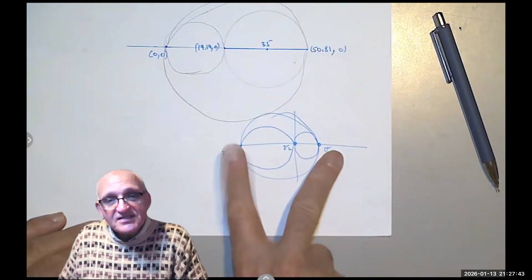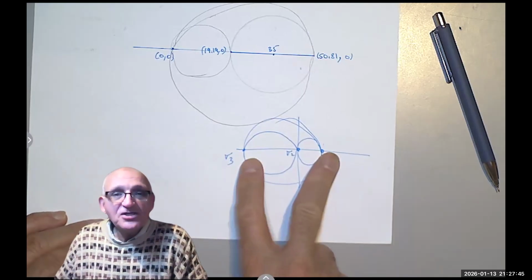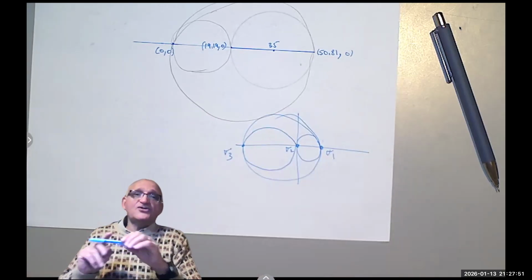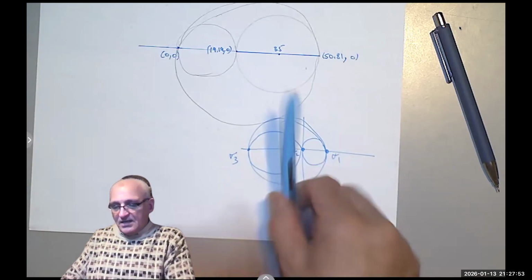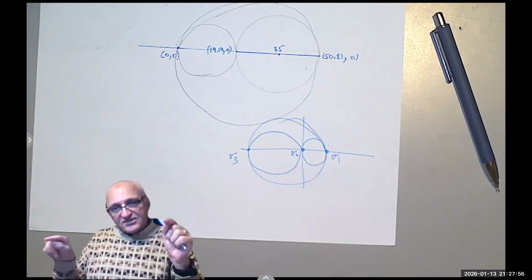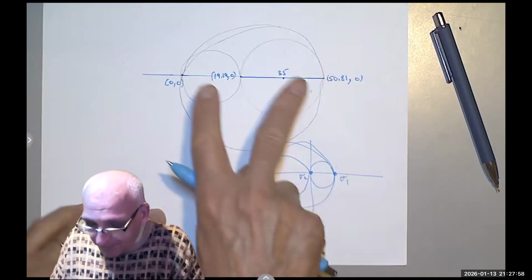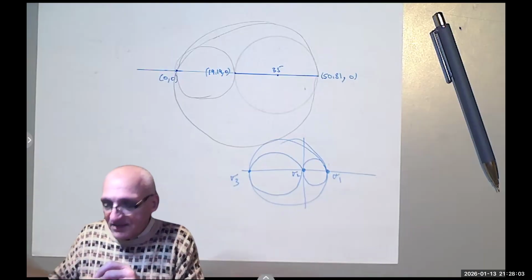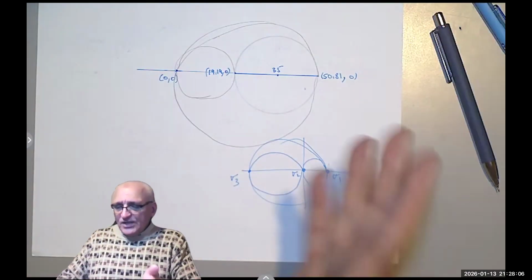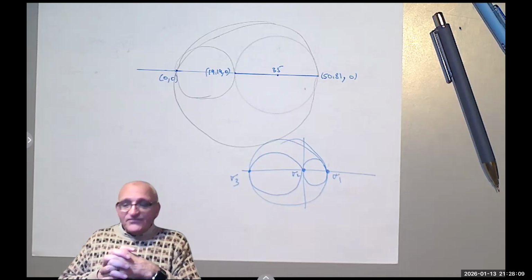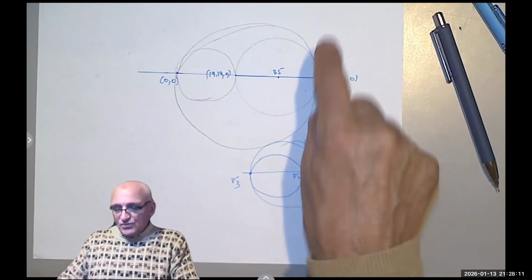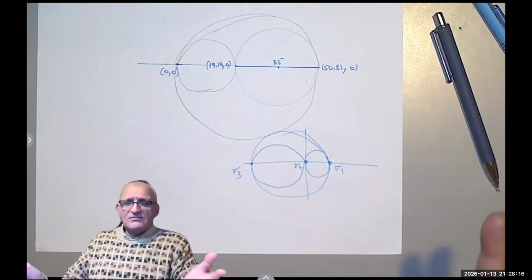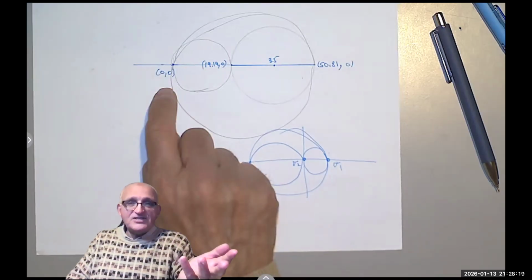So if one is positive and the other is negative, the maximum shear occurs in the xy plane, 45 degrees from the diameter sigma 1, sigma 3. But if both are positive or both negative, the maximum shear would occur outside of the xy plane. In some problems, they give you sigma 1, sigma 2, and sigma 3, and all of them have stresses, so not one of them is 0.